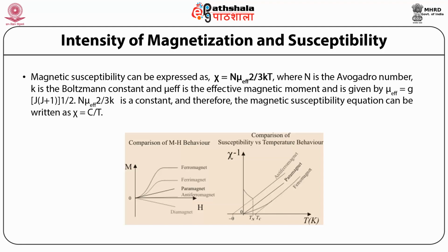This critical temperature is called the Curie temperature, known as Tc, and ferromagnetic material below the Curie temperature exhibit magnetic moments aligned parallel to each other. All the atomic moments are essentially aligned, giving a net magnetic moment even after removal of the external magnetic field.